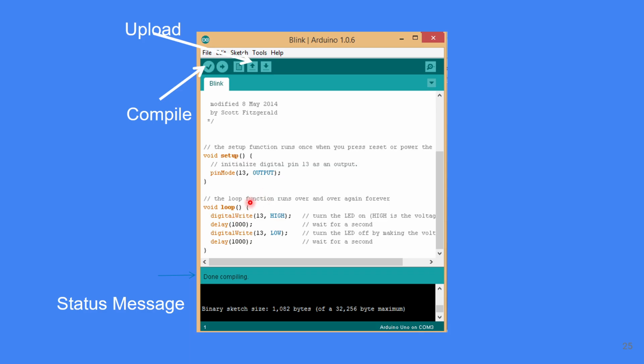So what we do here is we assign the pin mode, it is a syntax, pin number 13 as an output. And then in the loop, we write this pin as high, meaning it should be 3.3 to 5 volt, and then we delay 1000 milliseconds, which means 1 second, and then we digital write and make it low. So basically 5 volt goes down to 0 volt.